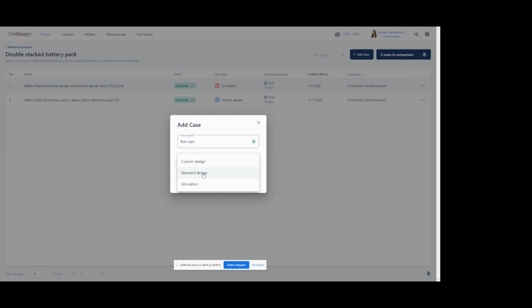This means that the designs that come out of it can be pins or fins. The third option is a custom design. For a custom design, the optimizer has complete freedom and it can return shapes besides pins or fins, but it takes into account your manufacturing requirements. For example, if you want to 3D print it, if it needs to be a stamped sheet metal cold plate, if it's die casted, and so on. But I will show you examples of all those 3 options so that it will be more clear for you.